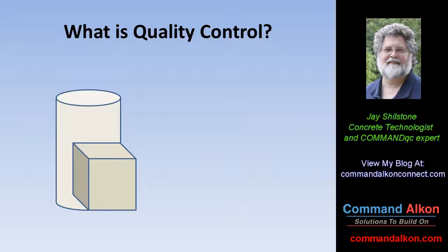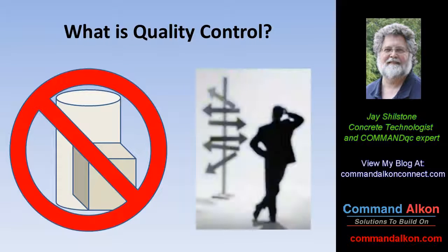What is quality control? Many people think concrete QC is about making cylinders and cubes, but it's not. Concrete quality control is about making decisions. Do I need to change cement content? What admixture should we use? What caused a low-strength test?